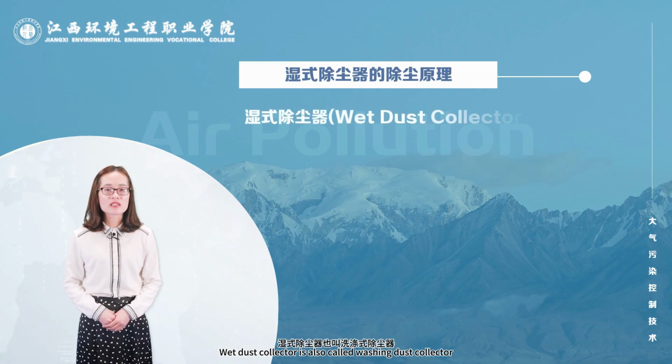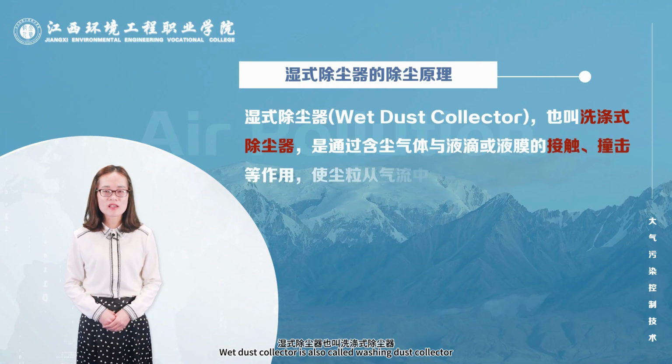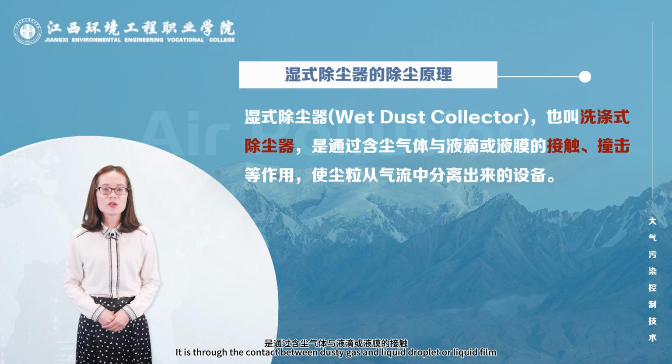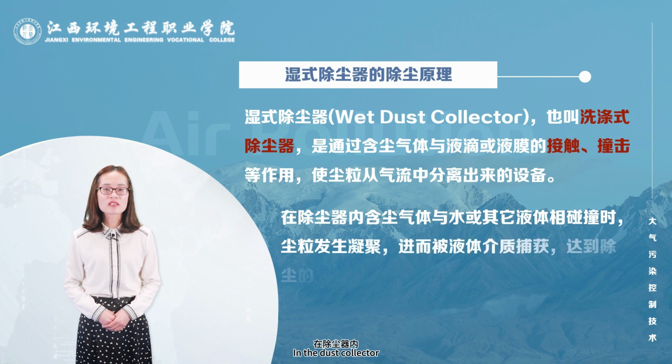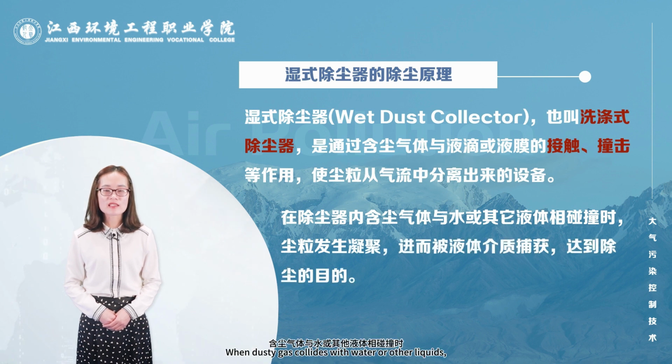Wet dust collector is also called washing dust collector. It is equipment for separating dust particles from airflow through the contact between dusty gas and liquid droplet or liquid film, impact, etc. In the dust collector, when dusty gas collides with water or other liquids, dust particles condense and are then trapped by the liquid medium to achieve the purpose of dust removal.